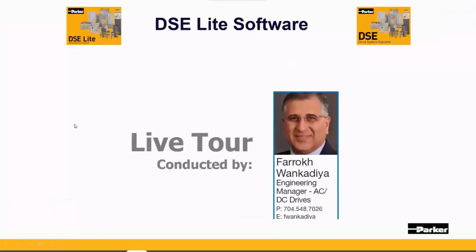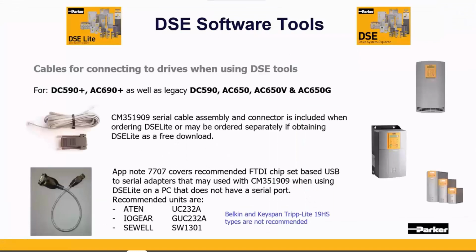And we have a few minutes left. I wanted to cover a couple other points that are useful to know about the DSE tools, and some of which really comes down to things like cables and whatnot, right? So there's a lot of different ways to connect to our drives. Some of the older products, like the 590 Plus and 690 Plus, have an RJ45 connector for programming. It's referred to as the P3 port, and